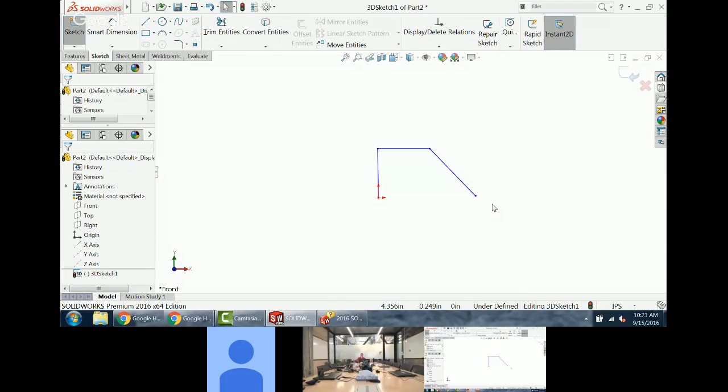So there's a situation where I needed to move in a particular plane that's not purely an XY plane. I couldn't control that plane. I mean, that's not purely XY or ZY. How I will typically, if I've got a situation like that, there's a couple ways of doing it. One, you could actually build a plane out there and lock the point to the plane.